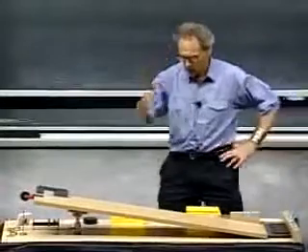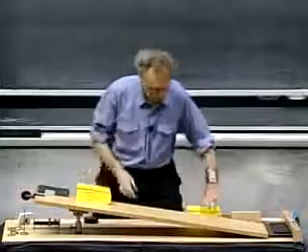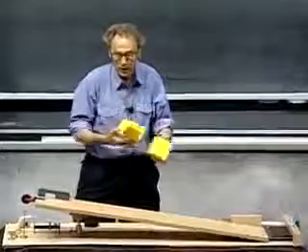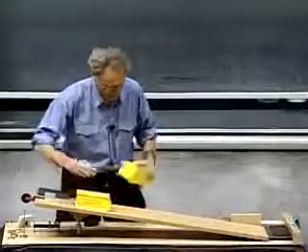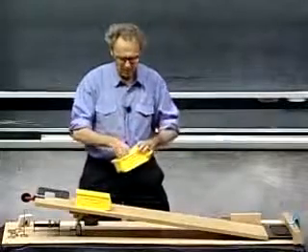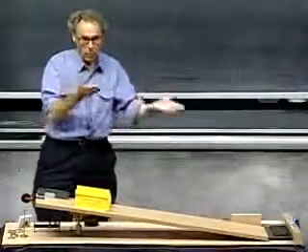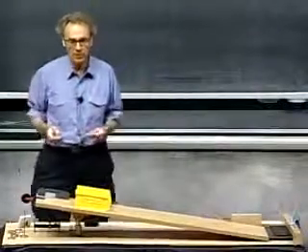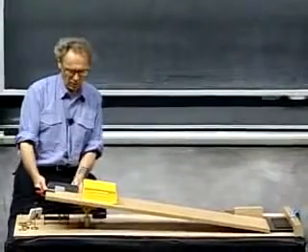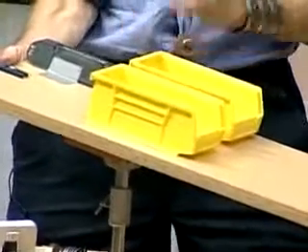I told you that the friction coefficient is independent of the mass of the object. I have two identical bins here. Well, as far as they can be identical. Maybe the bottom of one is a little rougher than the other. But in one, I'm going to put 200 grams, which is about 5 times the weight of the bin. Then, within reason, when I tilt them, they will go at the same angle, because it's independent of the mass. So let's try that again and see how close they are. It may be off by half a degree or 1 degree, of course, because the plank is not uniform everywhere.